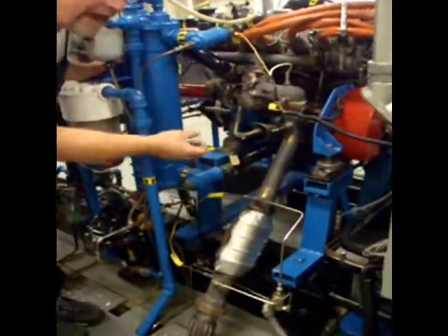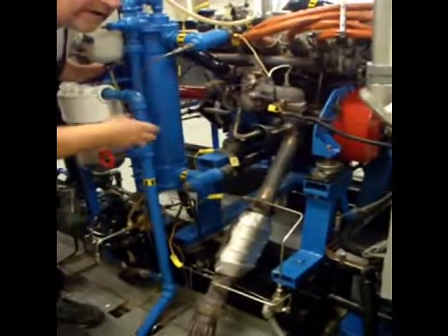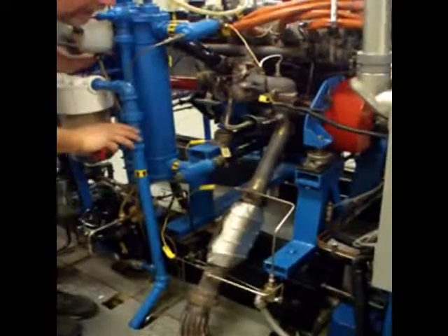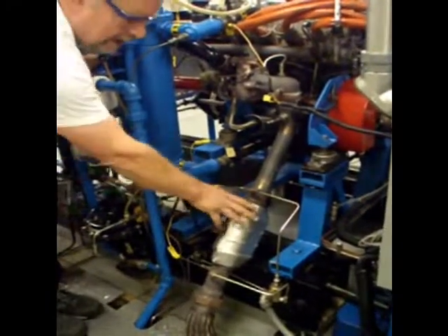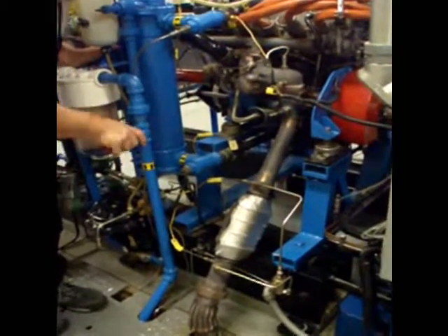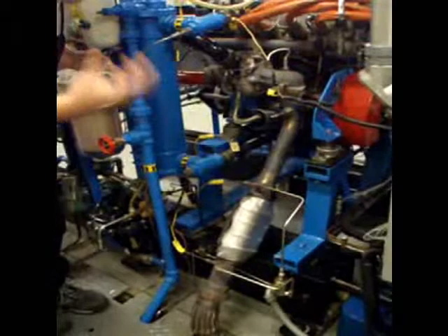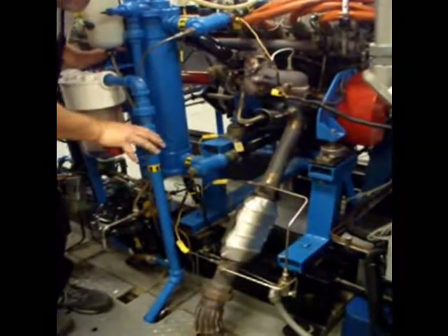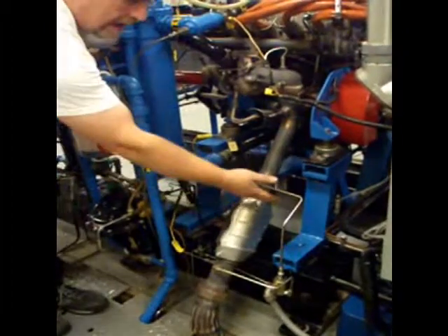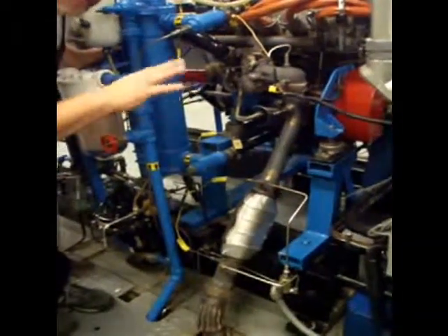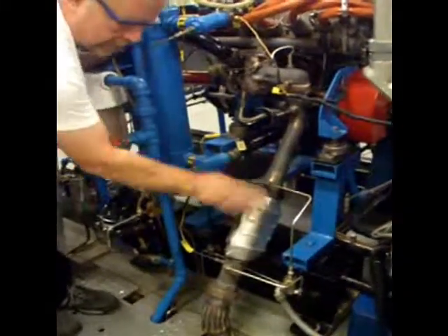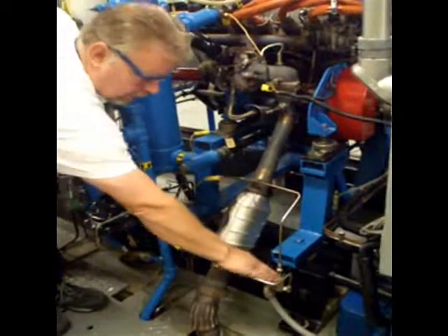So the burning of that, the combustion process, creates a lot of harmful chemicals and gases, in particular NOx. The catalytic converter is actually a device created to reduce the emissions and convert them into less harmful chemicals. So in our laboratory setup, using the Horiba gas analyzer, and we'll go over that in a minute, we can sample the emissions before the catalytic converter and after the catalytic converter using the solenoid.